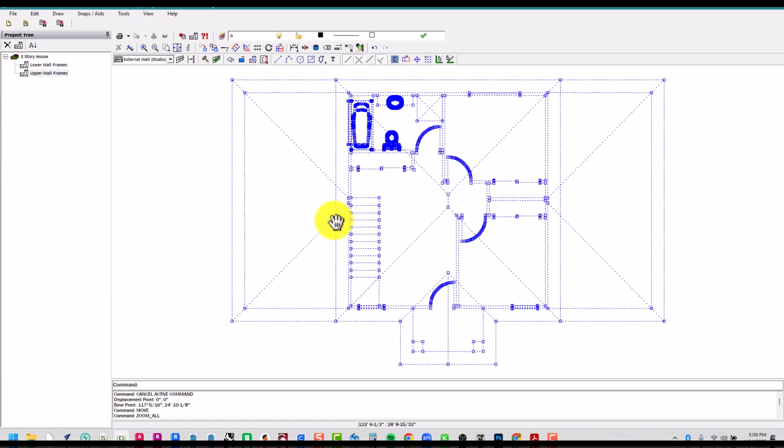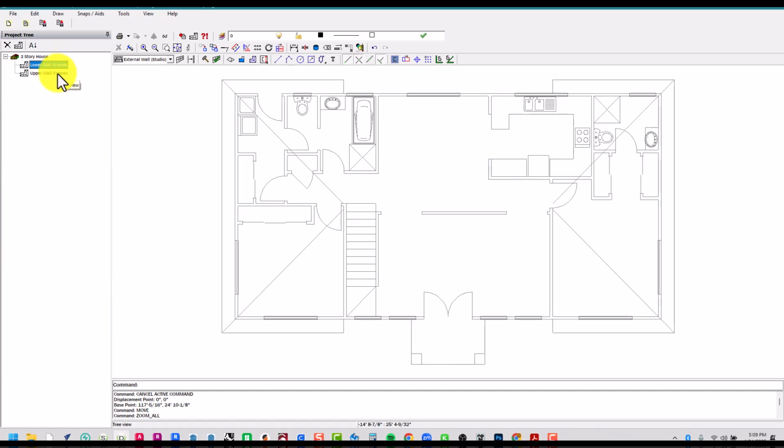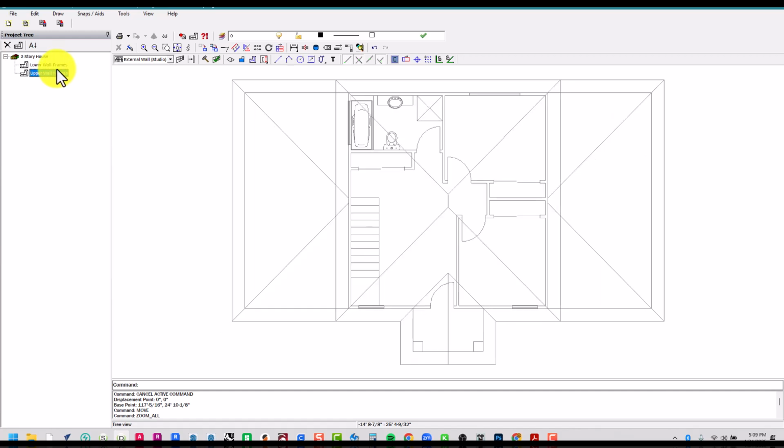Okay, double click on your middle wheel button to zoom full extents. And now we have both of these plans, both oriented so that the bottom left corners of each plan is at 0, 0. And that's how we'll be able to synchronize where our walls go in 3D. Okay, make sure you screenshot each one of these frames and submit it for the assignment. Thank you.